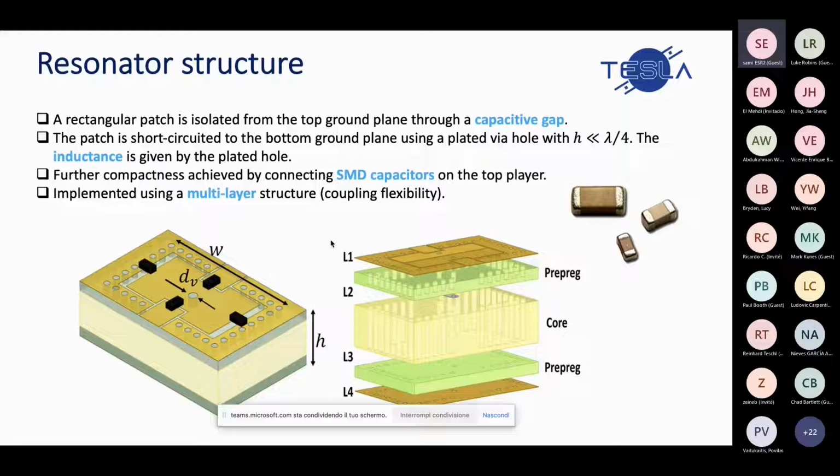That's why SMD capacitors have been connected from the resonator patch to the adjacent ground plane. In this way, we obtained an additional degree of miniaturization and the possibility of post-manufacturing tuning of the filter response, to adjust it in case the dimensions change due to manufacturing tolerances.